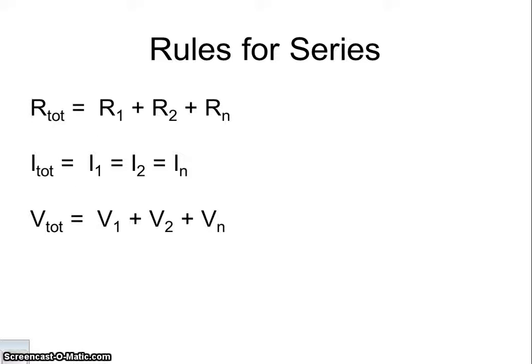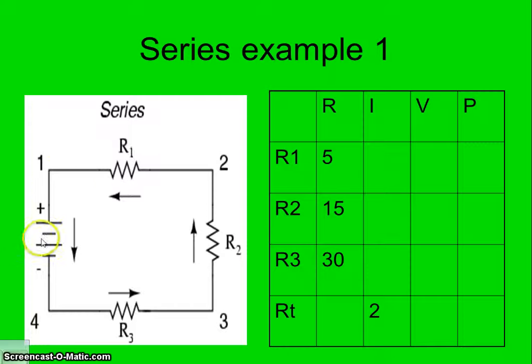And I'm going to make reference to them because I'm going to keep referring back to them when we are taking a look at some of the schematic charts. Alright, this is the symbol for a battery. Here, the long line is positive, the short line is negative. And your electrons are going to come out of the negative terminal. And this is a resistor. Okay, this could be almost anything that you would put in, whether it be a light or an appliance, they all have resistance. So this is a resistor and it goes through there, through this resistor over here and then back into the battery.